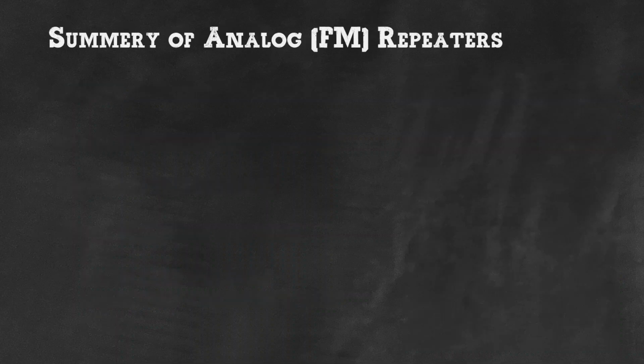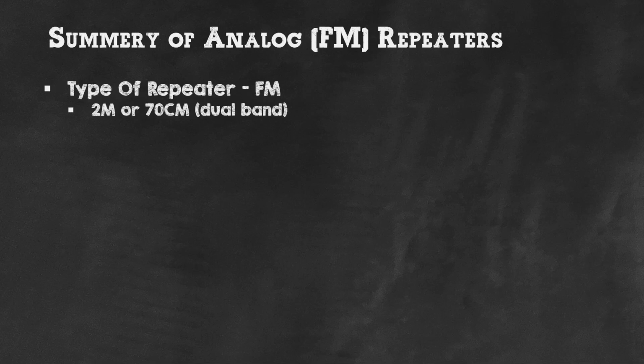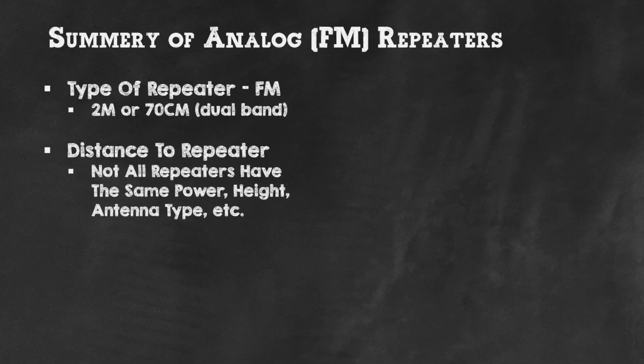So, summary of analog repeater, things you need to walk away with from this video is, okay, so what? What matters from this? There are different types of repeaters. There's FM, there's digital, but within the FM, analog, you're going to pick the 2 meter or the 70 centimeter. The majority of us are dealing with dual band radios. Those are the 2 bands. Distance to the repeater matters, but not all repeaters have the same power, same height, same antenna, so you're going to have a different experience. Don't think of them as equal. There are going to be differences between the repeaters: one might be closer to you, but you may not be able to reach it as easily as the one further down because it has a higher antenna and more power.